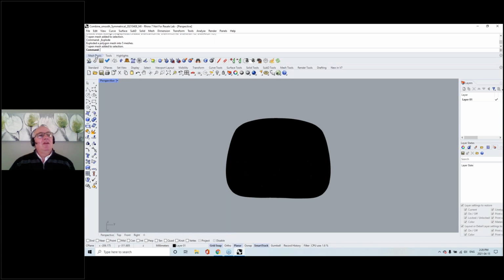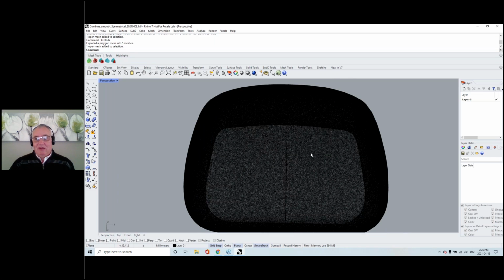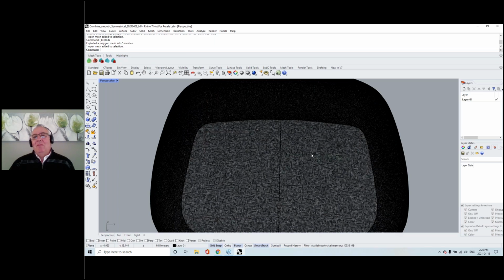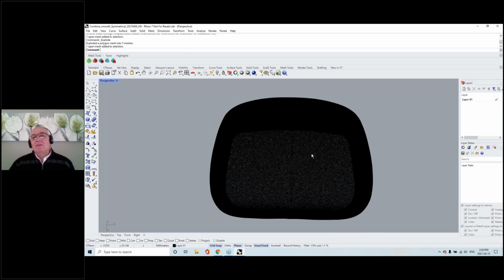And in the Rhino version, we have our meshing tools, we have our flattening tools, and we have our highlight tools. So our meshing tools, as Peter showed, this is a fairly dense mesh. It's a nice mesh. What we're going to do is adaptively remesh this. And what ExactFlat's going to do is take this mesh and decimate it down to a mesh size that's easy to handle for ExactFlat, but it's not going to lose any fidelity of the mesh.